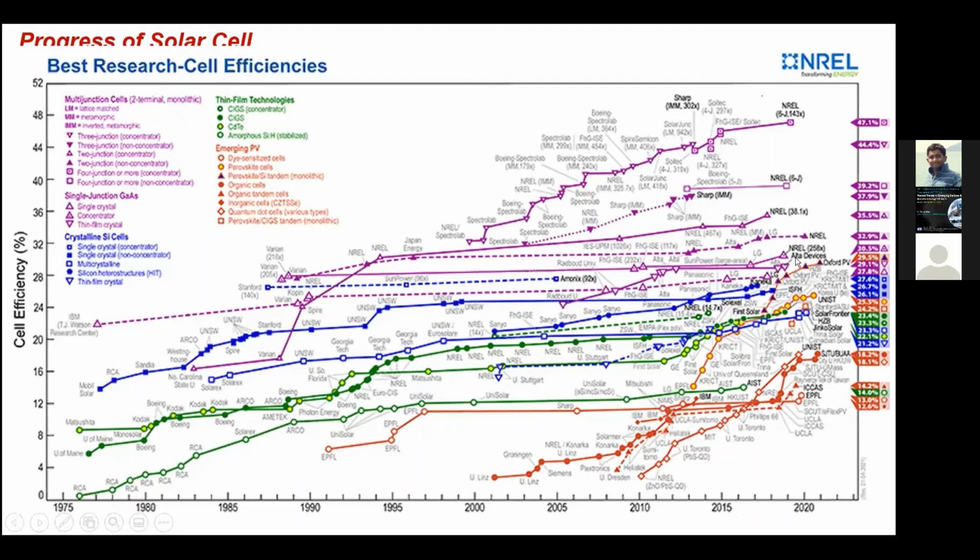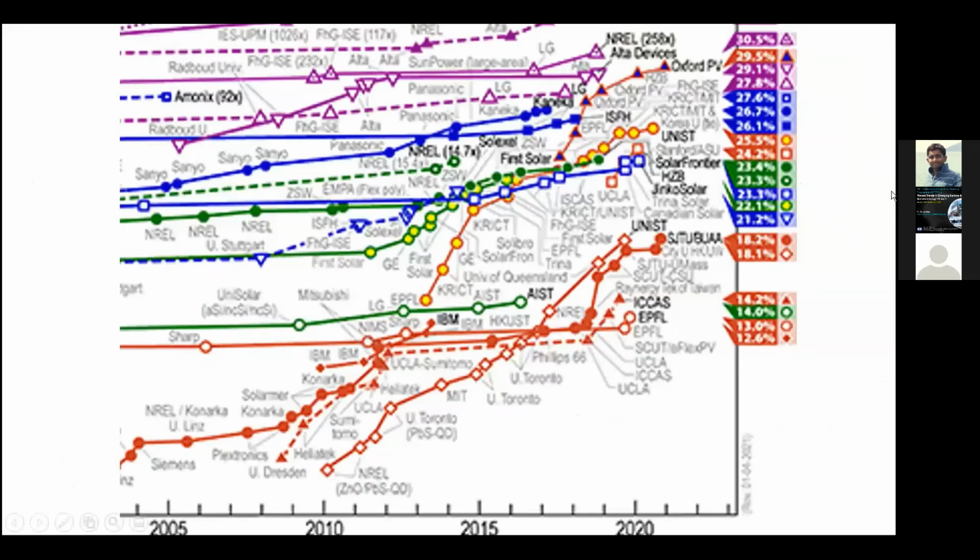This blue line is silicon-based solar cells, and this red rectangle covered with blue is a perovskite solar cell. These are also perovskite, but tandem kind of perovskite solar cells, perovskite made with silicon. If I zoom in, you can see we can have more than 29% efficiency using the perovskite material, and it crosses the silicon solar cell.